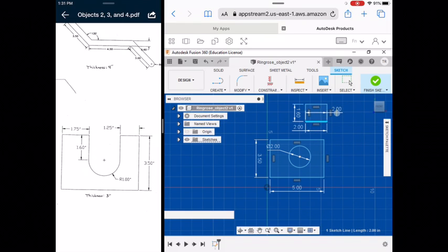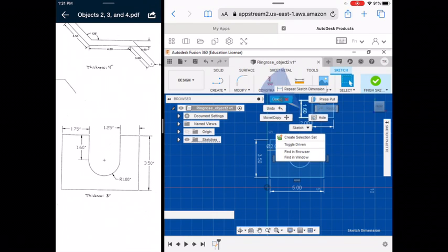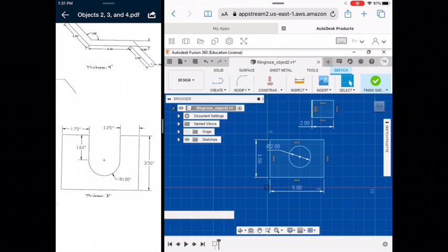Because I still have that tool option on right now, cancel. Because I have dimensions for both the vertical and horizontal, I can grab on any part of this and click and drag, and it's going to move the object. If I only had one of the two, and I were to click and drag on a side that's not confined, it's just going to move that. And grab the center of the object. It's going to move everything with it.